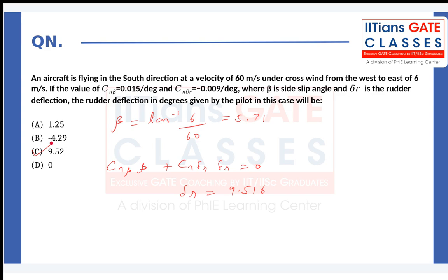Dynamic stability. Okay. Try to bring that up. Anything else? Will the aileron deflection produce favorable yaw? Okay, so the main primary control surface for adverse yaw correction is the rudder. But I don't think aileron will. What do you mean by favorable yaw? So when you deflect the aileron, it does produce a yawing moment also, and you need to deflect the rudder to